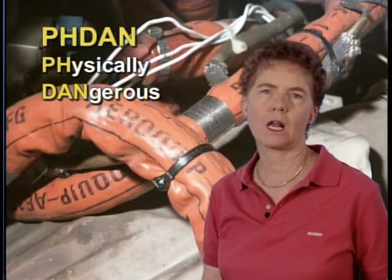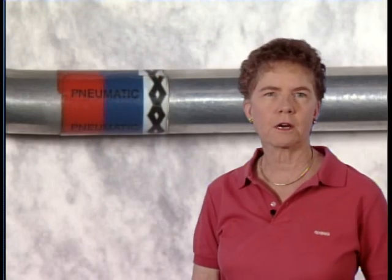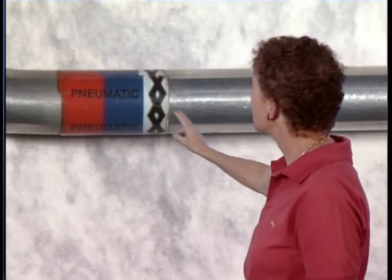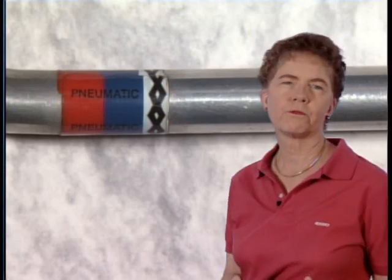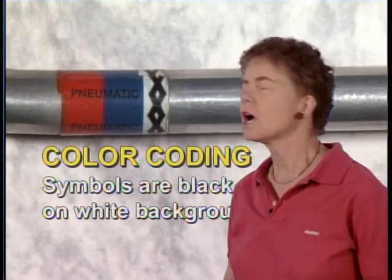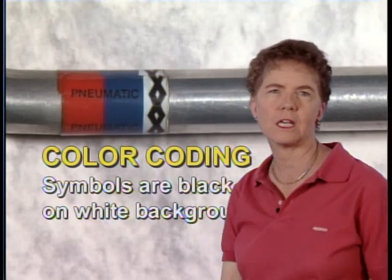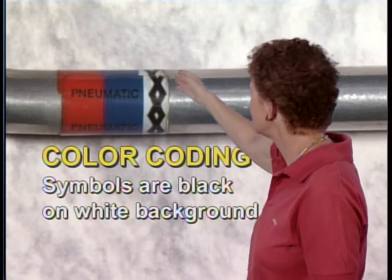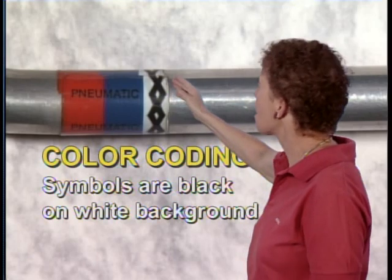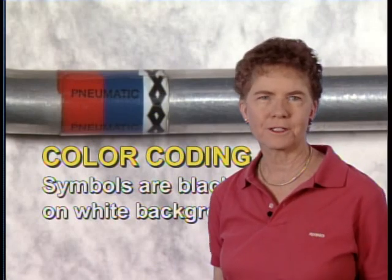Now, because the plumbing lines may be fairly long on large aircraft, they'll identify them at regular intervals with color-coded bands and with geometric symbols unique to each type of fluid system, and that helps avoid confusion. The FAA wants you to know that although the colors of the colored portion of these bands will vary depending on what kind of system it is, the geometric symbols, and these geometric symbols change depending on the kind of system, the geometric symbols are always black on a white background regardless of the contents of the line.